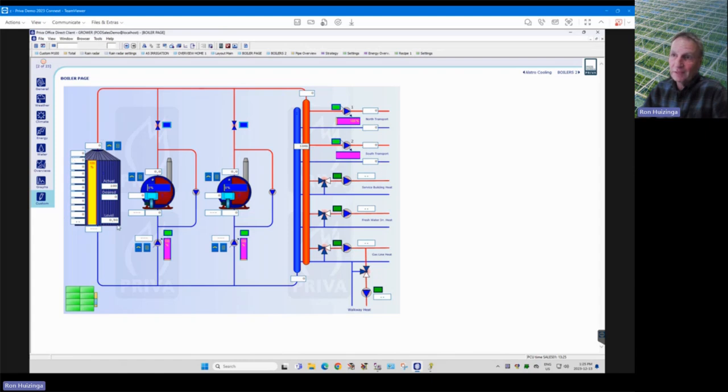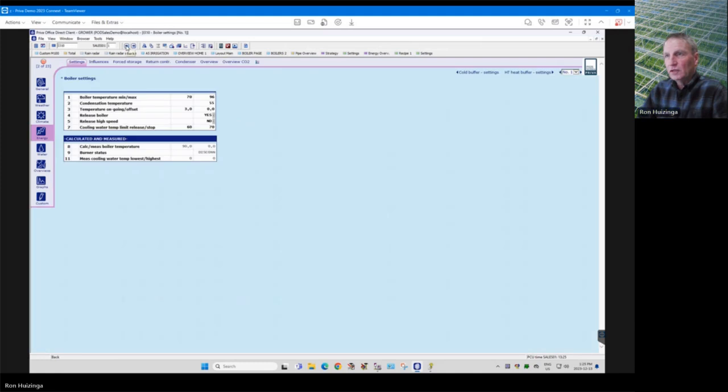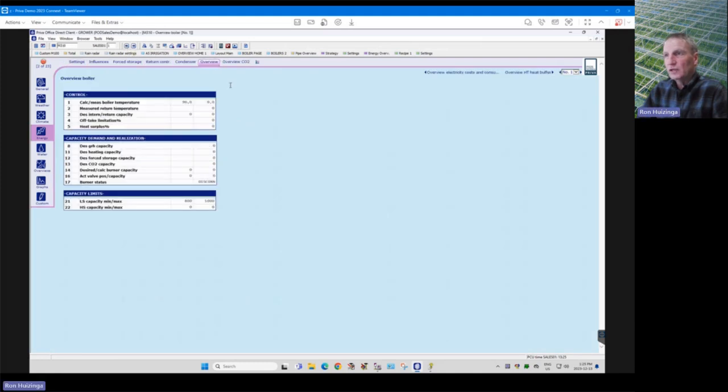But if you don't have a buffer tank and you have that system set up, then with the boiler, if it drops in temperature, you still need heat in the greenhouse. So the boiler valve will stay open and heat the greenhouse, but that off-take mixing valve has a calculation here, off-take limitation. So how much heat you can take off the boiler, that number will increase. And when it goes to 100%, it's actually closing all the mixing valves in the greenhouse.